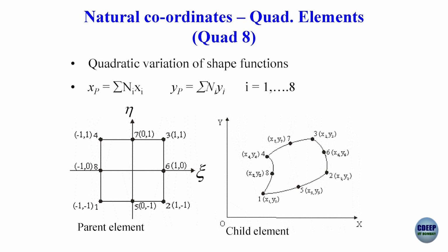So I would do the double integrals evaluation, limits will be always -1 to 1 for both zeta and eta. So that is the advantage I am going to retain for the computation purpose. With the real physical world, I will distort it and try to map curved geometries, boundaries. Still there will be discretization error. It's not something that you would be completely able to eliminate. There is a new error that has crept in now in our finite element modeling.